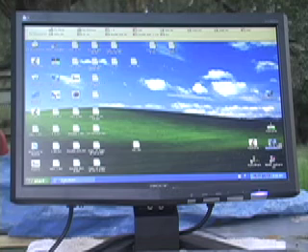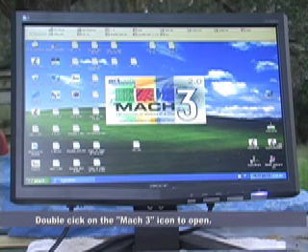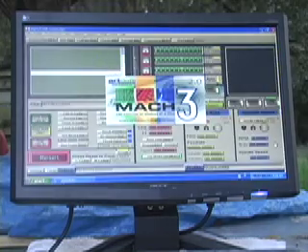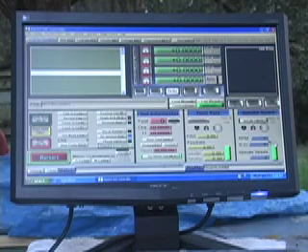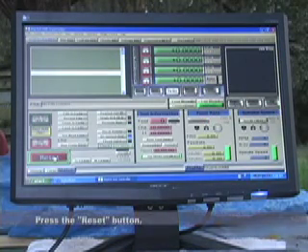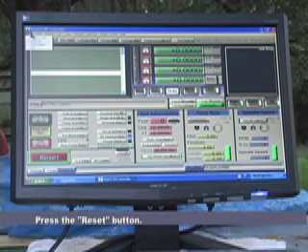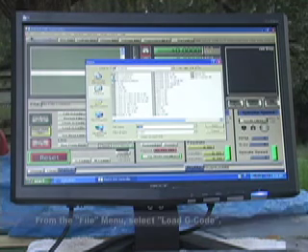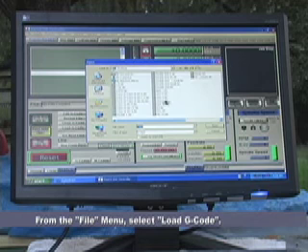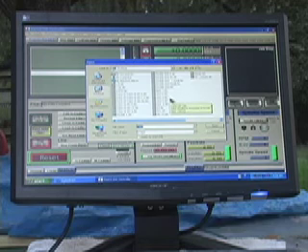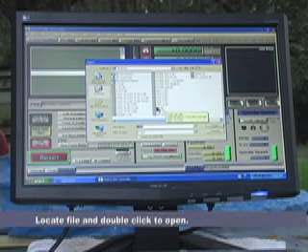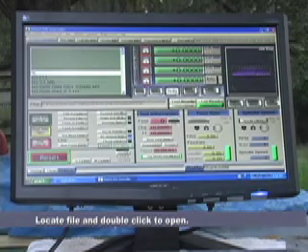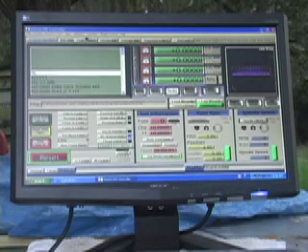If we go down and choose Quantum Mill or Mark III, we'll open up the actual program to do the machining with. Click on Reset. Go to top left corner, load G-code file. Desktop, we're looking for V3, which is right there. And there's our part shown here.